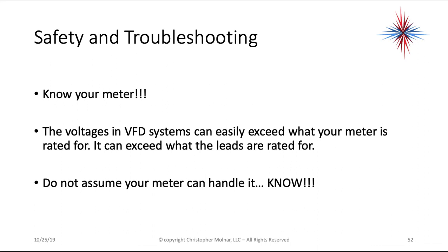Know your meter. The voltages in VFD systems can easily exceed what your meter is rated for. It can exceed what the leads are rated for. Do not assume your meter can handle it. Always check the documentation for your meter. I have one meter that I use that can only handle 600 volts. Well, I obviously am not using it on VFD systems.